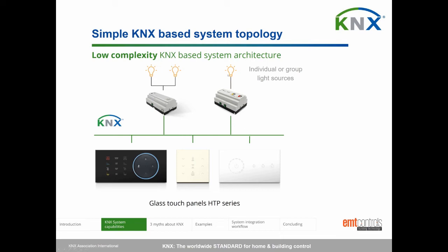Two lamps are driven by a KNX actuator that can turn them on or off. Now this actuator is getting commands straight from the touch panels. The actuator regulates giving the power from mains to the lamps. However, the digital part of the actuator is commonly powered from the KNX bus. Our third lamp will be driven by the dimmer. So now we can control the brightness of the light from the touch panel, since it's already a standalone solution.